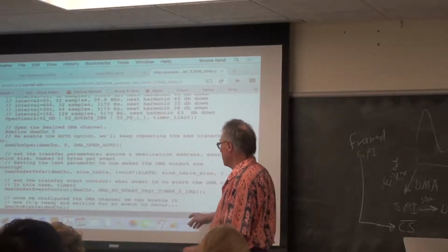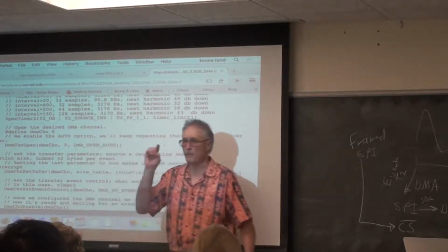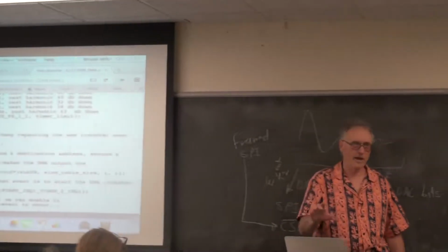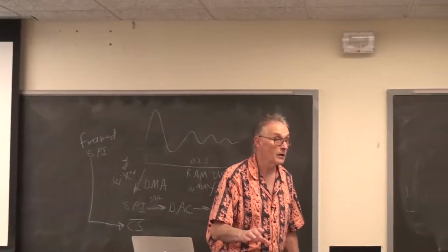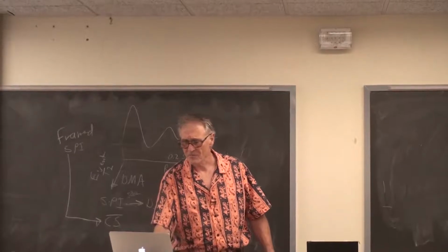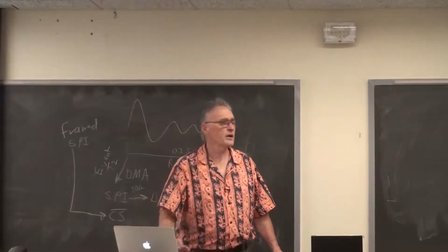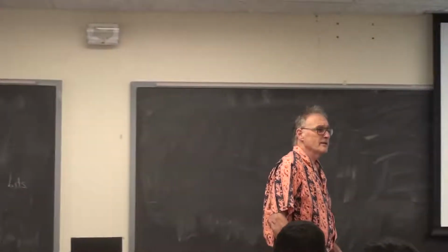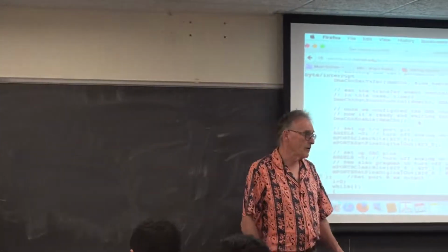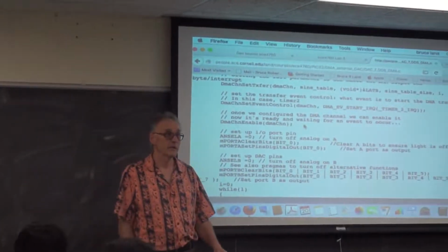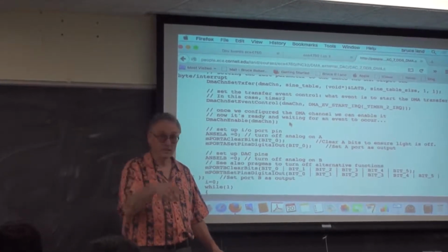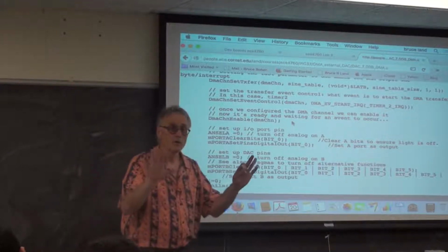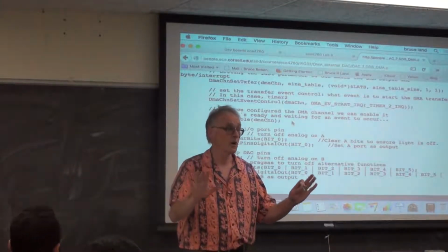And now that we've configured it, we enable it. As soon as we enable it, boom, it starts to make the sine wave. No code in main, no code in the thread, no code at all. And this is what hurts the head, because you just have to remember that this thing is making a sine wave. There is no indication. Oh, you can read the channel descriptor and find out that it's actually sending bytes. You don't have to completely memorize it. But as soon as you start it, no more software. It just runs.